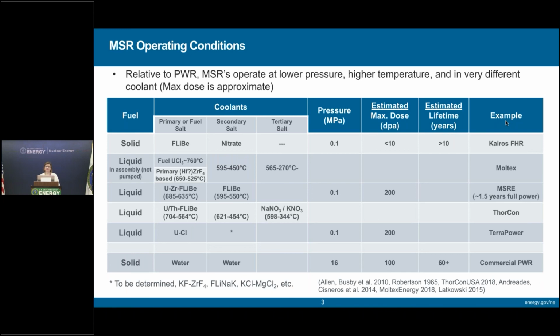Is IASCC an important criterion to be addressed? Yes, it is. Do you want to take this one, Sam? Yes, obviously the irradiation-assisted stress corrosion cracking phenomenon is more well developed or understood or observed in, for example, light water reactors and in other materials. So as far as the molten chloride fast reactor applications, we have less information on whether or not IASCC is a degradation mode.